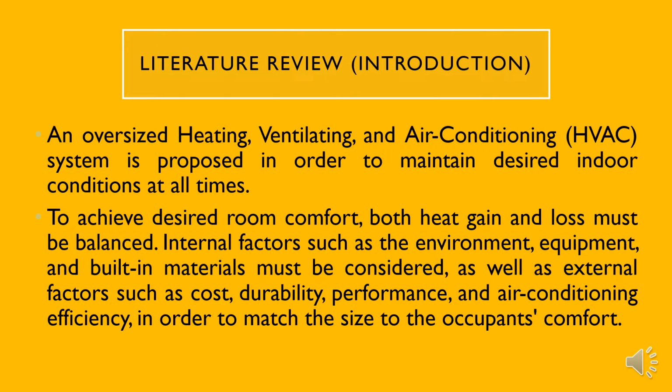An oversized HVAC system is proposed in order to maintain desired indoor conditions at all times. Regardless of the weather condition, the system will operate at partial load for the majority of the time, resulting in lower efficiency. To achieve desired room comfort, both heat gain and loss must be balanced. The objective is to make the classroom interior space as comfortable as possible for the occupants. This is only possible through the use of an appropriate method.